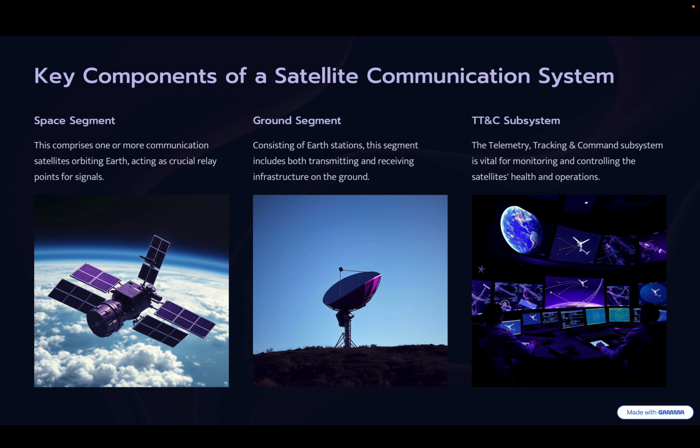whatever changes we have to make to the signal so that it can be propagated to a satellite, all those changes such as multiplexing, modulation, encryption, and assigning the power to the satellite, all these processes will take place at the earth station, and then the frequency is converted to the uplink frequency. So if you want to communicate with a satellite, we can communicate only through the uplink frequency.